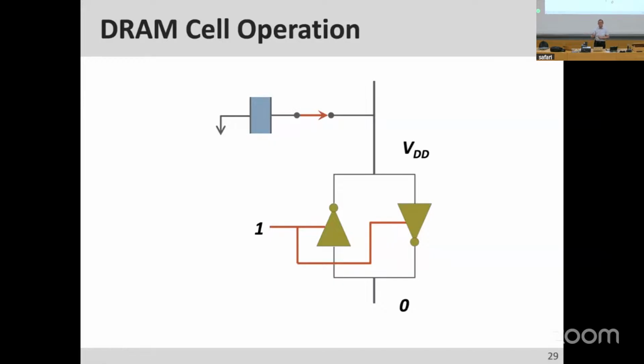Of course, these operations take time. It takes nanoseconds to make this work, because this is really small. If the DRAM cell was much larger, it would be faster, actually, because a lot of charge would get out and things would operate faster. But a DRAM cell that's large is not good for capacity. Today, we want huge capacities for many reasons, machine learning being one of them, but many applications. If you want capacities to be huge, the cell needs to be much smaller.